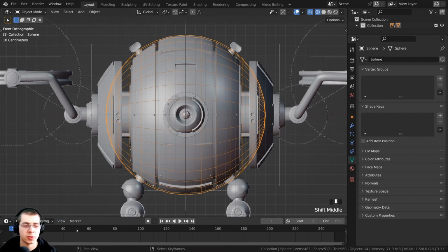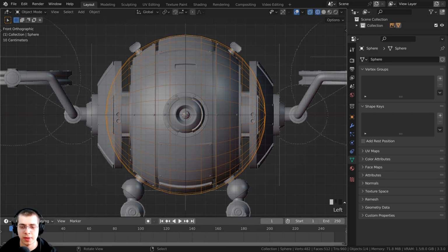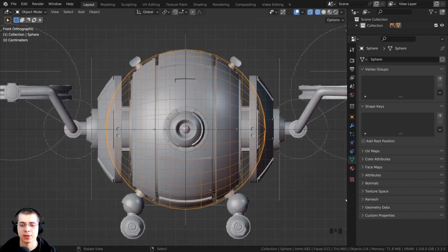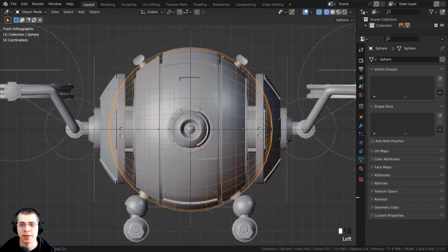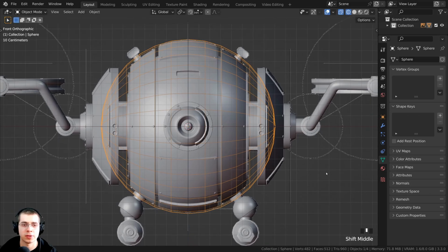And then also, we're not doing the animation right now. We will be doing the animation at the end of the tutorial series, but for now, we don't need the timeline. So what I'm going to do is click right here when the crosshair appears, and I can click, drag up, and then drag down, and let go, and that'll close the timeline. Let's also make this a bit smaller so we have some more space for the modeling.